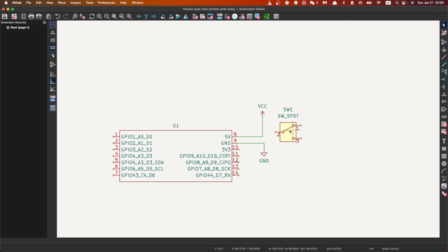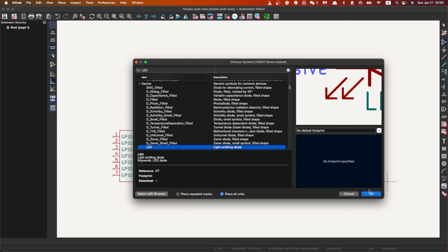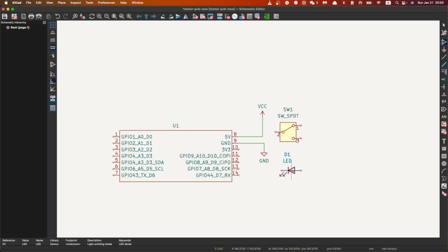So another thing we're gonna need is the LED. So let's add them correspondingly. LED, see, it is here. So pretty neat. And since we have an LED here, and it is connected in parallel with the MCU, this sub-circuit is actually directly powered by this VCC voltage. I mean, any LED cannot handle that without a protecting resistor. So that is super important.